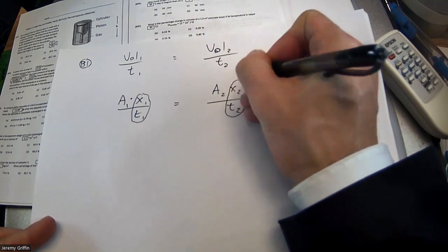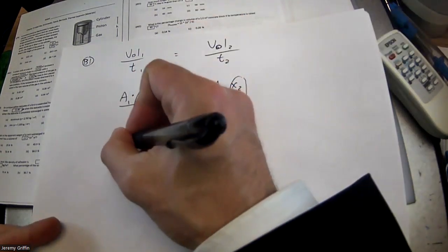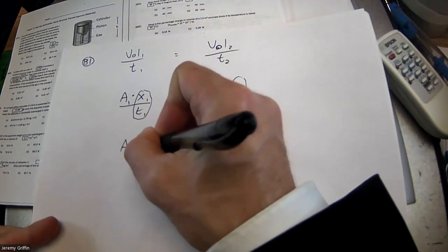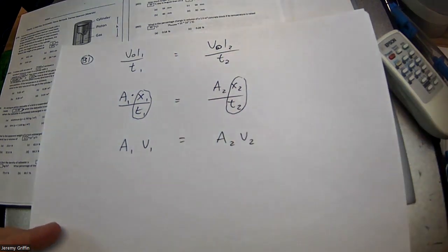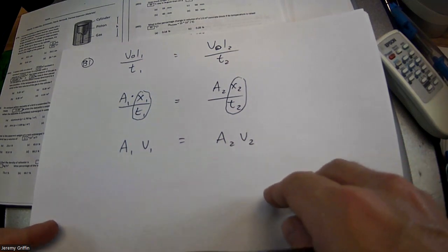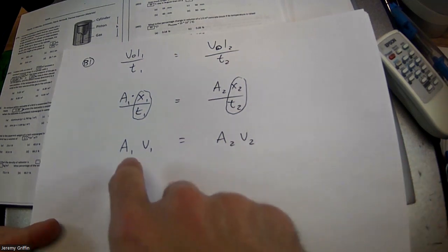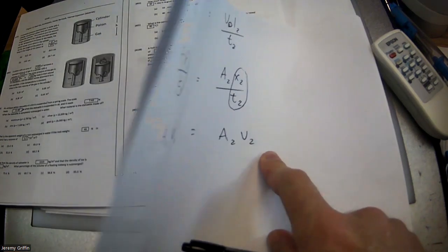So what is distance per time? What's that called? Like velocity, speed? Okay. So cross-sectional area times the speed is also the same everywhere. Okay. So that's the version of conservation of flow that we're actually going to apply to this problem, because I gave you 3 of those 4 numbers. Actually, did I? Yeah, I did.